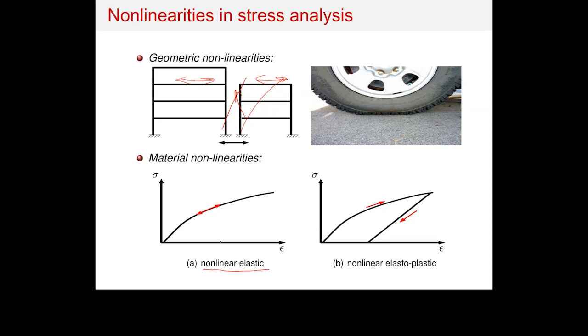I think probably later on, once you get into the concrete, Dimitrios is going to discuss nonlinear elastoplastic behavior. But what we are going to discuss now is nonlinear elasticity. Now, this is nonlinear because you cannot approximate it with one line. If you try to approximate this with a line, you will be missing quite a lot of the accurate behavior. So you will be severely underestimating the strength that this polymer can take when you approximate it as a linear behavior.